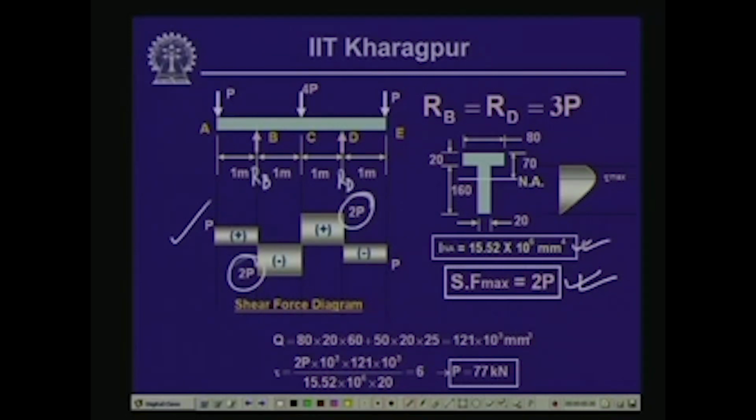Now, as we have seen, in the case of rectangular sections we get maximum shear stress at the neutral axis. For this rectangular component, at this particular section our shearing stress is not 0, but you will have some value which we call tau minimum, because you have some area for which you get the Q value, which is A y bar. When we took the rectangular section, above the top surface we did not have anything, and that was the 0 shear stress.